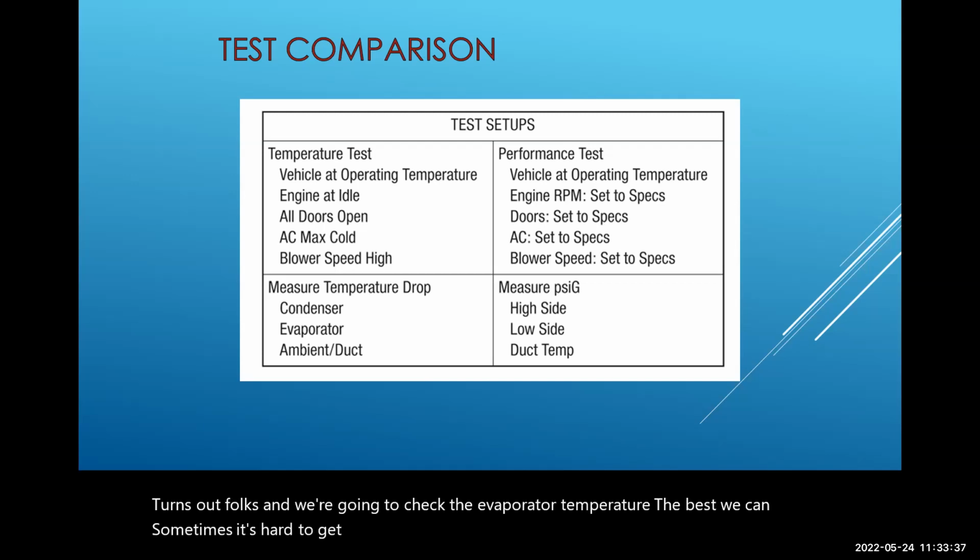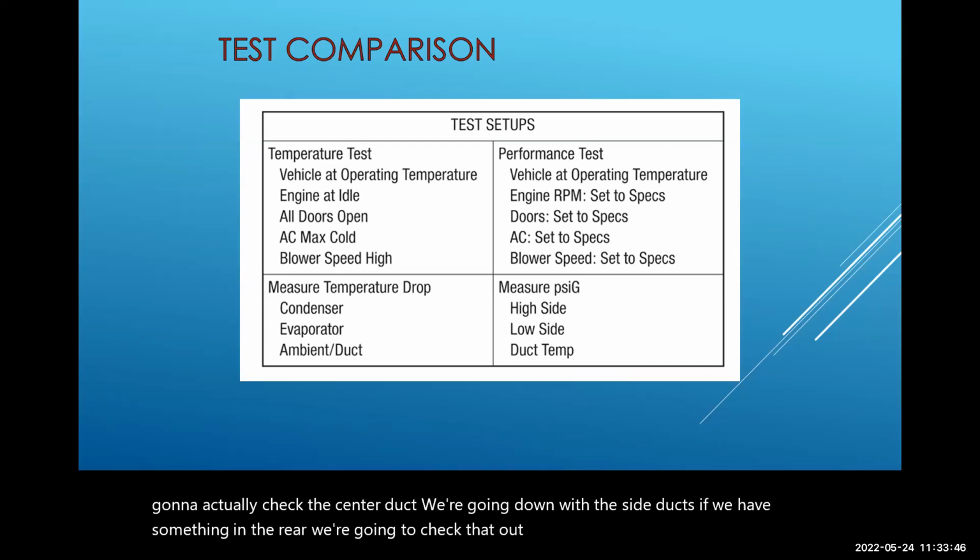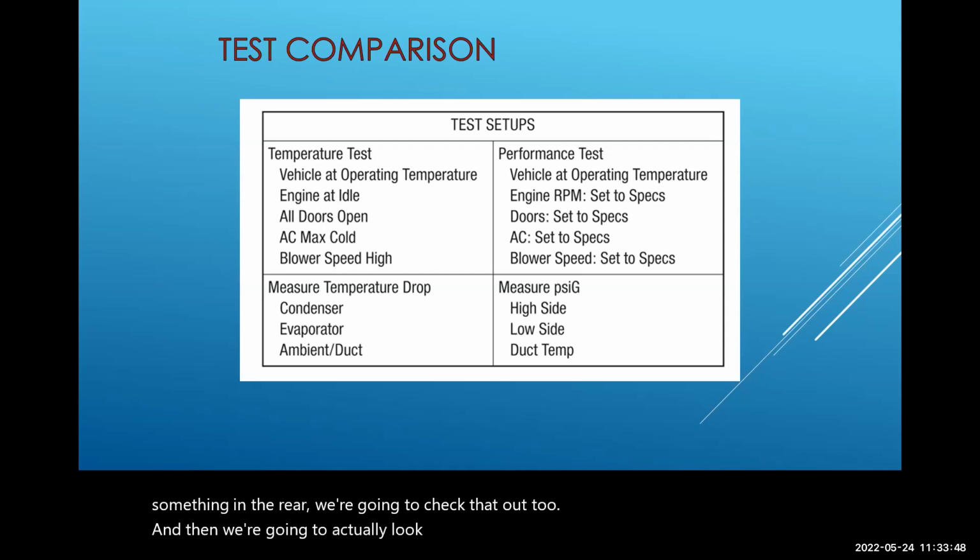And then also we're going to check the duct temperatures. We're going to actually check the center ducts. We're going to check out the side ducts. If we have something in the rear, we're going to check that out too. And then we're going to actually look at the high side and the low side and the duct temperatures too.